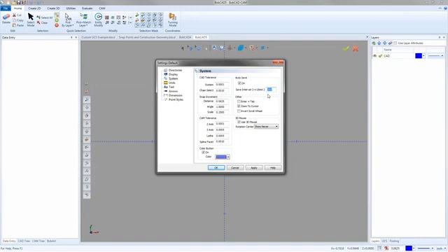It really depends on what you're working on. If you're doing a lot of 2D stuff where it's kind of quicker drawings, you're just doing a lot of them, I'd say save every 15 minutes. If you're doing bigger drawings where in a half hour's time you're really not getting that much stuff done, what I would do is I would use a 30-minute, 45-minute save interval. That way you're not screwing anything up in between. And then right down here we have some options.